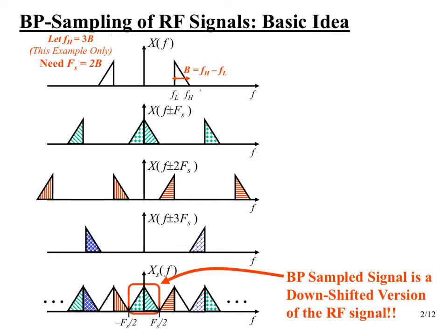what that analysis that we did earlier for standard sampling really showed us was that when we sample, we should think of the resulting spectrum as the original spectrum plus a bunch of frequency shifted versions. And they're shifted by integer multiples of fs. So that was what we saw coming out of that impulse generator halfway through the DAC.